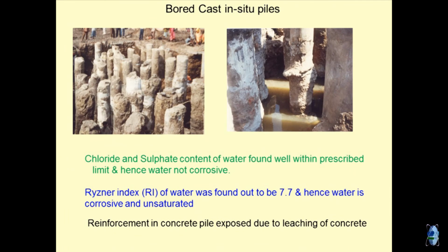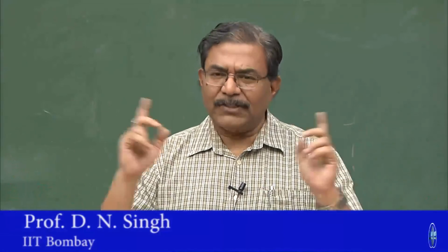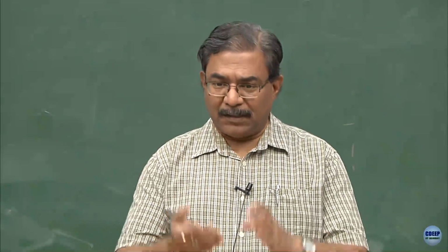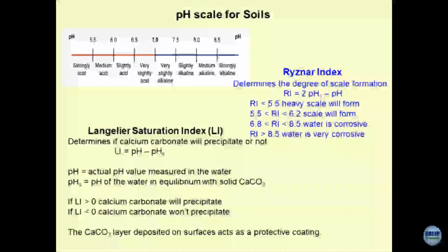I am sure you must have realized that these types of concepts were not discussed earlier in the subject. What we bothered about only was the bearing capacity, and we thought that bearing capacity is always going to be the same for time immemorial. But now what you are realizing is that the more and more industrialization is occurring, the more and more pollution is getting stacked over. This is a threat to the existing structures. So, this forces us to study the pH of the soils and the pH of the groundwater and the calcium concentration of the groundwater and so on.